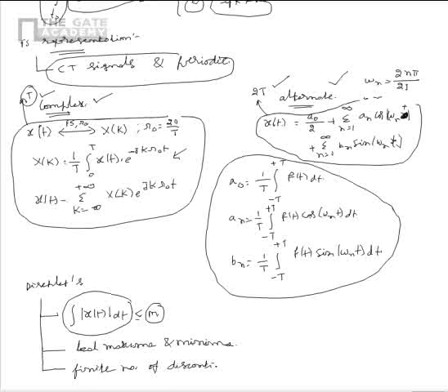So from here we see that for the Fourier series representation of a continuous time periodic signal to exist either in complex form or alternate form, Dirichlet conditions should be satisfied. They are: integral of mod of x of t dt should be finite, this is over one period.